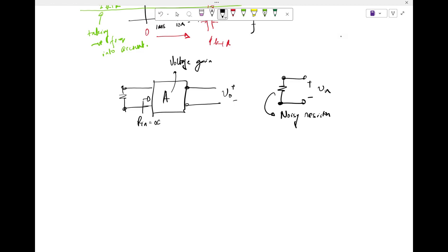If you plug in a voltmeter at the terminals, you are going to get some voltage, even though there is no signal attached to it, even though nothing is attached to it, right? So now, for circuit analysis, these types of representations are not particularly useful. We would like to keep the resistor as an element which always gives us V equal to IR. And if there is anything associated with it, we would like to remove it and make it a separate element out of it. That helps in circuit analysis.